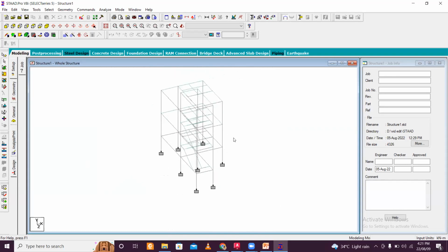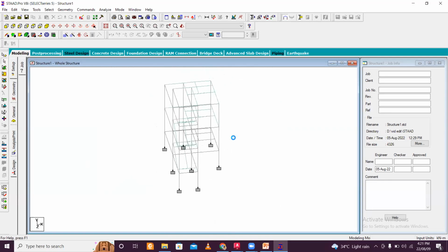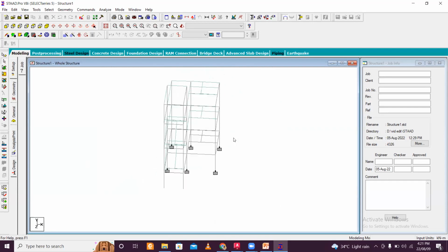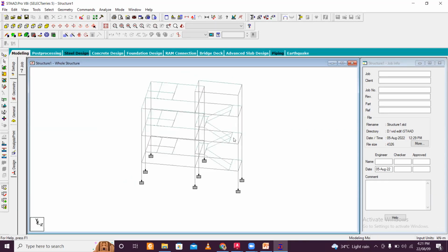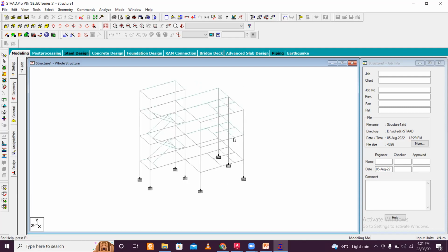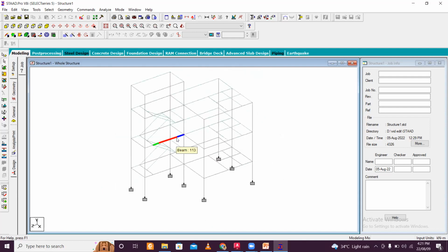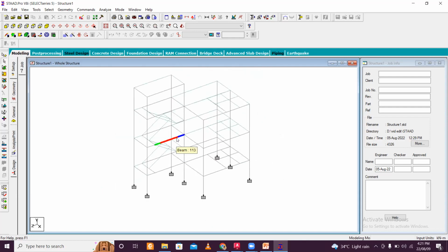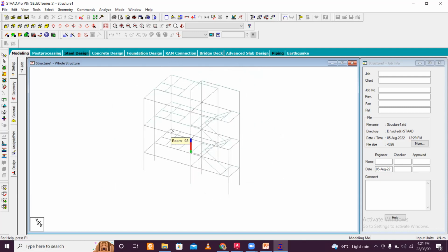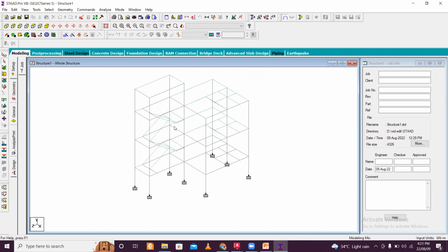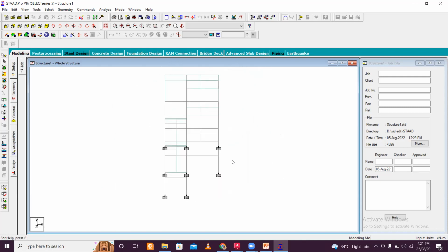When you are going for vetting a project, especially for government projects, either some other engineer, or professors of educational or government institutions, will check your STAAD model, and even some municipality approvals check it. So you need to make sure your model has all the load combinations and all the model delicacies considered, like I tried to tell you in the previous video.